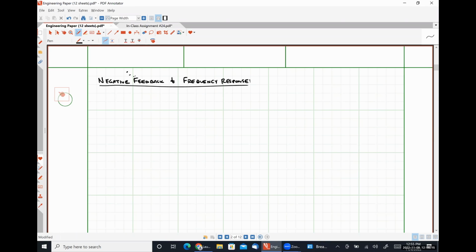And then the role of the other resistor, depending on the type of amplifier that we have, is getting beyond the scope of the course. Effectively, if we want to make our amplifier actually capable of linear amplification, not rail-to-rail outputs oscillations, we need to employ negative feedback, okay?